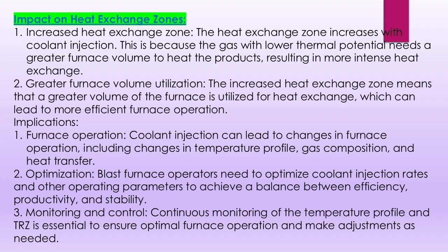Implications. 1. Furnace operation. Coolant injection can lead to changes in furnace operation, including changes in temperature profile, gas composition, and heat transfer. 2. Optimization. Blast furnace operators need to optimize coolant injection rates and other operating parameters to achieve a balance between efficiency, productivity, and stability. 3. Monitoring and control. Continuous monitoring of the temperature profile and TRZ is essential to ensure optimal furnace operation and make adjustments as needed.